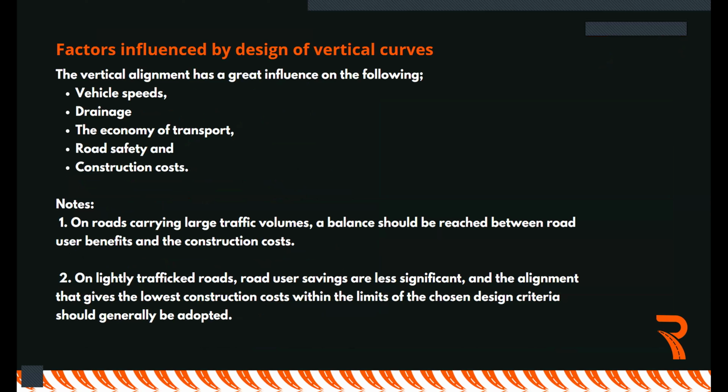No design can be implemented without you giving them the assurance that so and so is able to stop safely. That is very important. So these are some of the things that we look at. Vehicle speed. These are some of the things that influence design. If the vehicle design speed is very high, even in a mountainous section, you will need to lower it very much so that you achieve the same driving experience.